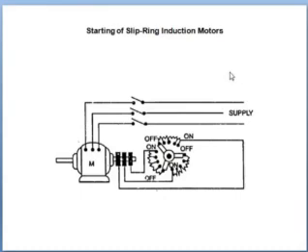Now, one thing here we have to discuss. Previously, we said that the slip ring induction motor has a special provision. We can use resistance in the rotor circuit across the rotor. If we use resistance in the rotor circuit in the slip ring motor, and the resistance in the rotor circuit is increased, then the rotor current and the reflected current in the primary are also reduced.